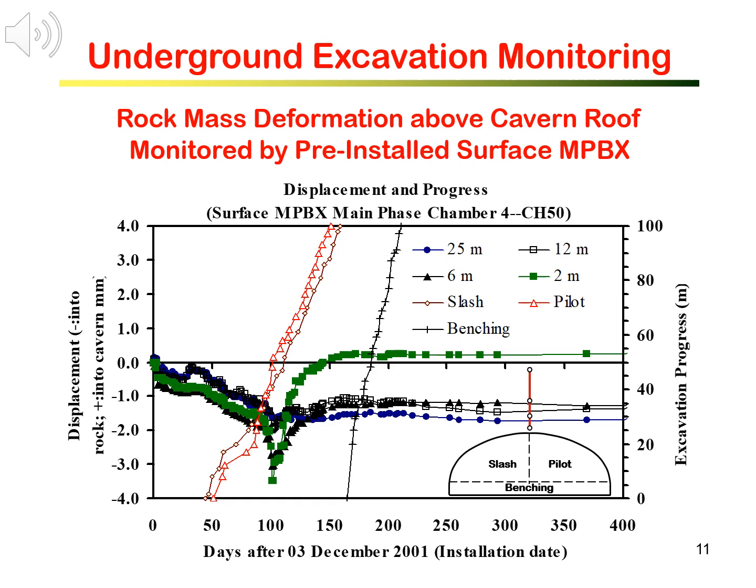I did it because I wanted to get a complete picture of ground deformation before, at, and after excavation. If the MPBX is installed from the tunnel wall, we'll only catch the deformation days after excavation. In hard rock, much of the deformation would have already occurred.